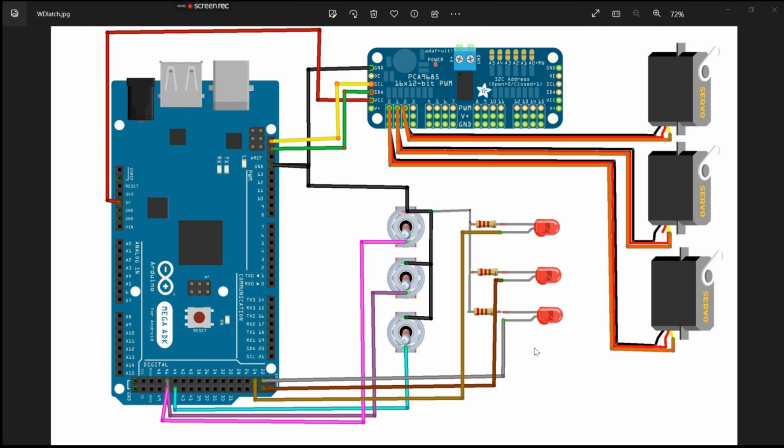If you've got a large layout, you've got lots of switches, lots of indicators, maybe signals, all sorts of other stuff, you're going to run out of pins pretty quick. So you'll want to add I/O expanders for sensing the inputs on the switches. You can also add additional PCA 9685s to drive the servos. I'm sorry, the LEDs. They'll drive them as well as the servos.